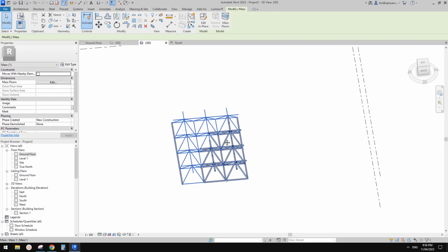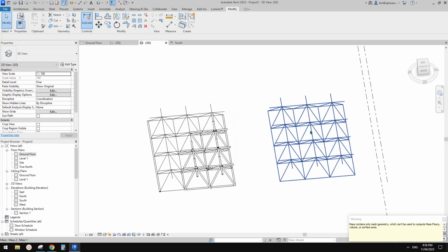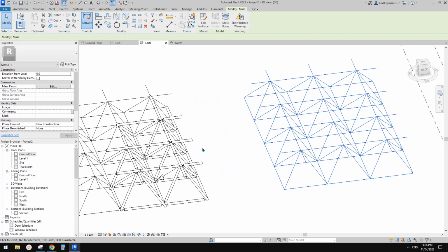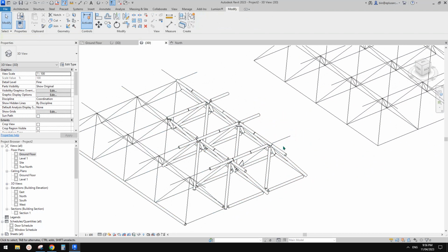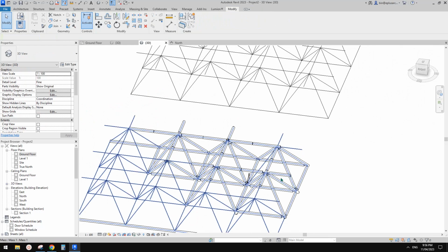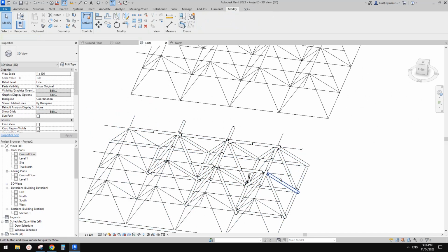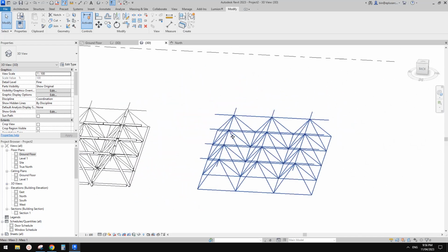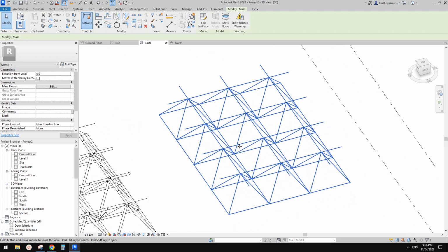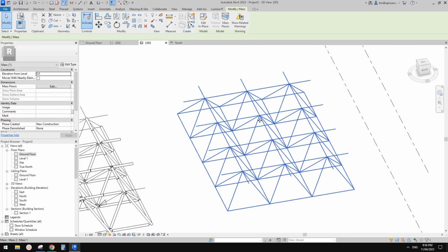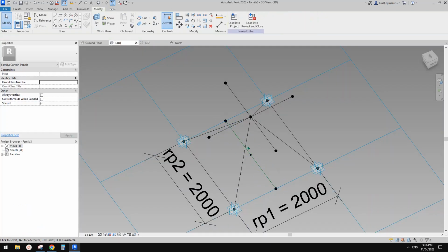The other one is, I'm going to copy this one here so it's easier, and leave it here. Also, we don't need this actually. In here you can see there's no extra one, because it's all placed manually, so it's very easy. You just don't place that. So the other method is we're going to directly place all these tubes inside of this pattern-based family.